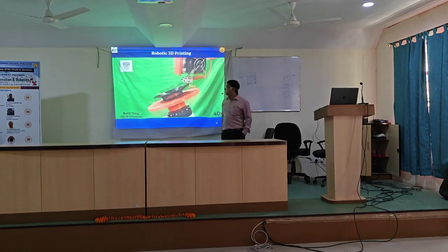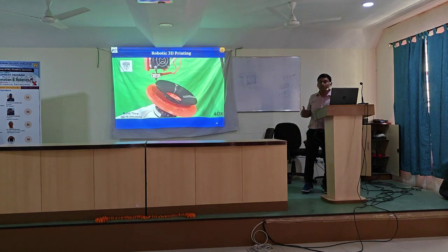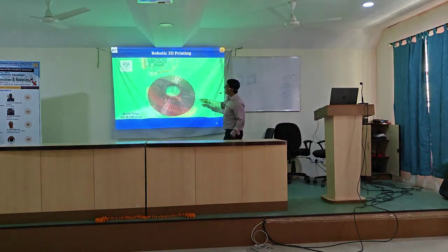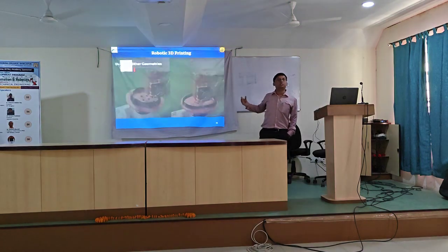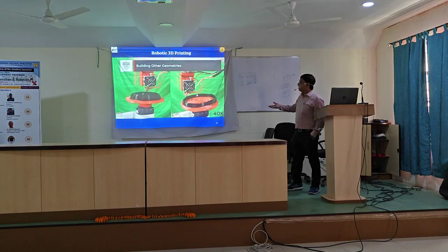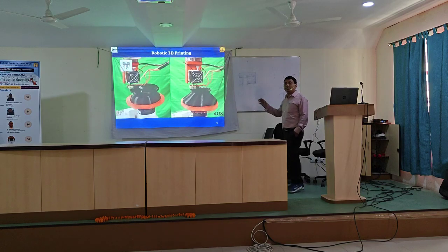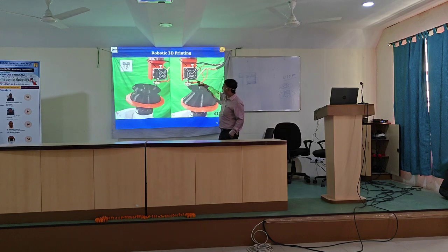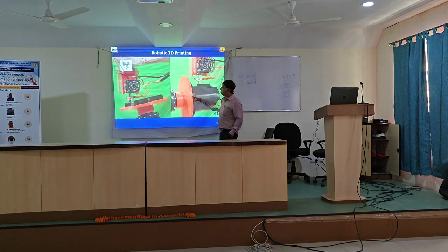So that is the interesting thing. This robotic additive manufacturing, or robotic 3D printing, is now becoming very popular because it can create support-less 3D printed components that were not possible previously with traditional CNC-based 3D printing. The 3D printing that I have shown previously for mask making and others is the traditional CNC-based Cartesian 3D printing system. And this one I am talking about is robotic 3D printing. The process is the same, FDM, but it is robotic 3D printing.